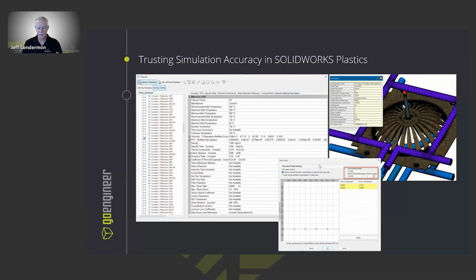So if you have an existing process and you can enter all of this process data, we can go as deep as actually using screw diameters and screw positions, which most of the modern injection molding machines now, that's how you set your shot sizes and things like that, based on the screw diameter and the positions, and then your screw speed for your injection. So instead of just using a specific pressure, we can do that. And we can also do profiles. So you can get really deep into the process as well.